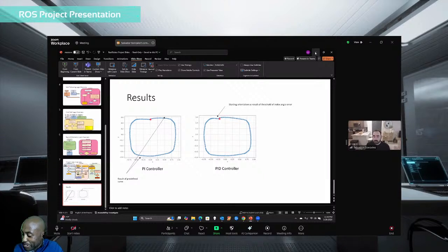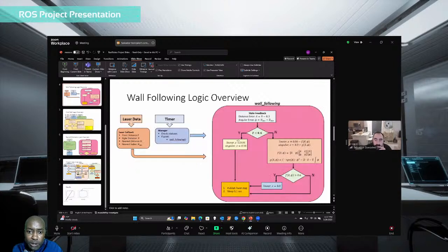The other thing I wanted to ask you about is you spoke about using corner actions, right? So it's almost like you put a separate control measure for all the turning that your robot will do. Can you give us a little more background behind that? Why did you choose to separate that control algorithm from the general wall follower? Because I think it will still turn when it realizes that the threshold is below 0.3, right?